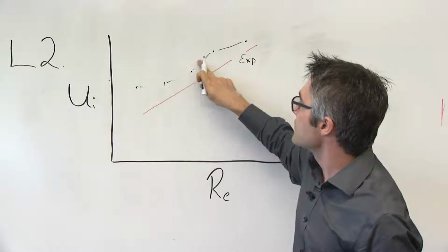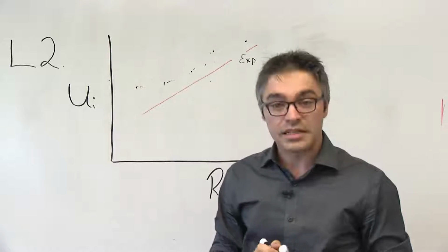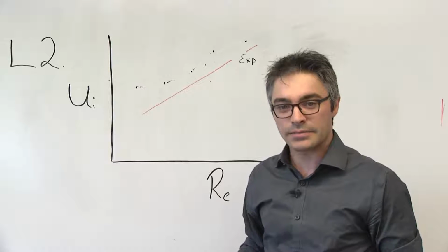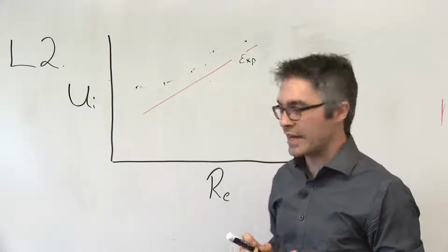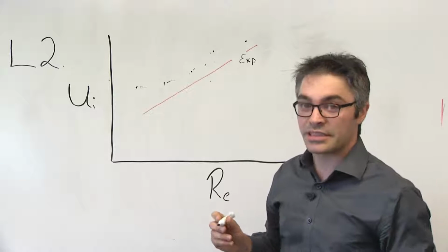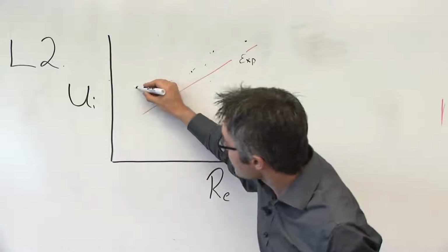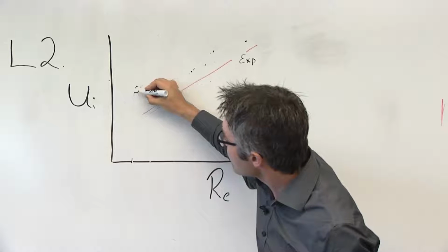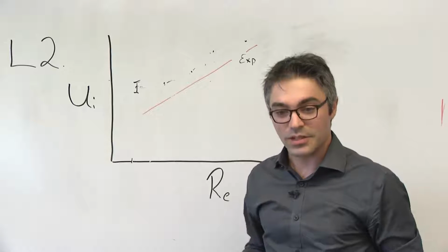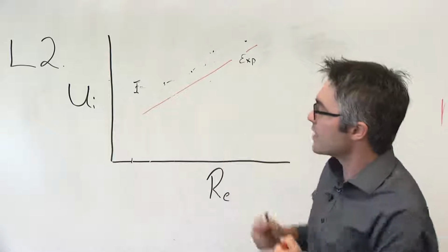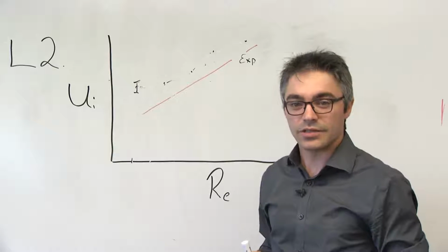Single data points tell a far better story than improperly used trend lines. If you have the option to repeat data, such that you can get a standard deviation for a single point of a Reynolds number, please give us an error bar showing your standard deviation. This will result in an overall better display of what you're actually able to find and achieve during the experiment.